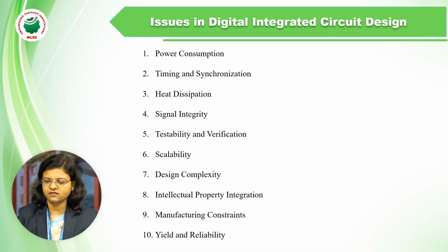In clock gating, we have to disable the clock of a certain portion of the circuit which is not in use. Clock gating mainly reduces dynamic power consumption, and power gating is basically for static power consumption, in which we completely turn off the circuit or some portion of the circuit which is not used at all. In this way, by using these techniques, we can minimize the power consumption.